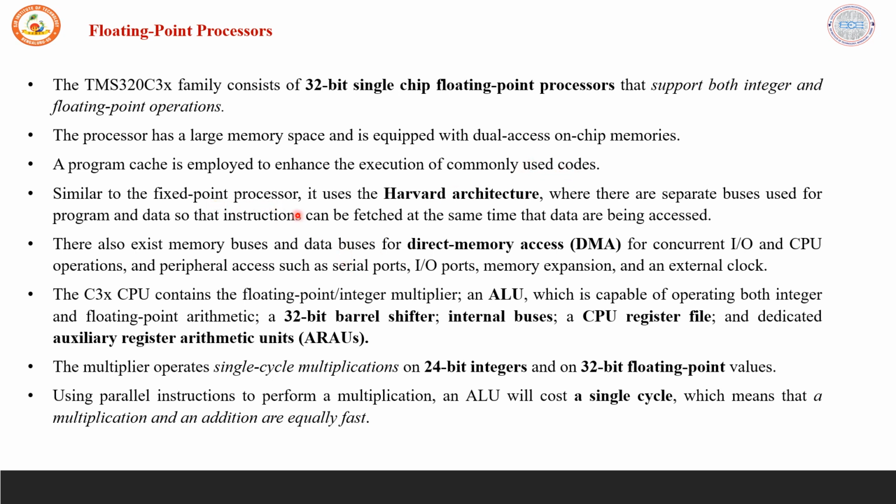Similar to the fixed point processor, here also we use the Harvard architecture, where there are separate buses used for both program and data, and hence instruction can be fetched at the same time that the data are being accessed.